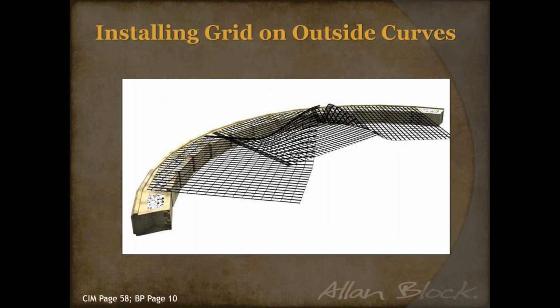And most grid companies out there, when I talk to their technical assistants, they say grid on grid could be a little bit of a slip surface. So now all of a sudden you don't have that interaction with the soil, and it's not as desirable as you're getting that gap or that overlap. So what we want to do is just simply lift the top layer of grid up, put about two or 3 inches of material between there, and then put it right back down. That way we've got the grid soil grid interaction and not that slip surface that they worry about. But again, no gaps, no overlaps.